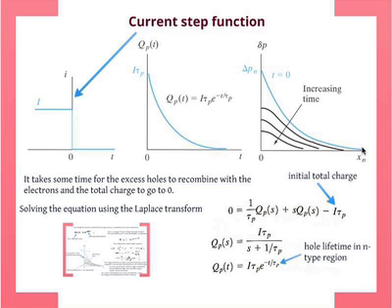Now the question is, how do they change with time? We know they have to go down because they recombine. Remember again, the physics is that you don't have carrier injection because you turned off the current. So the only thing the carriers can do now is diffuse and recombine. And they'll go away. In fact, that's what you see: the peak goes down because it's diffusing away from the peak and also recombining with lots of electrons there. It's an N-type material, remember. Lots and lots of electrons hanging around.